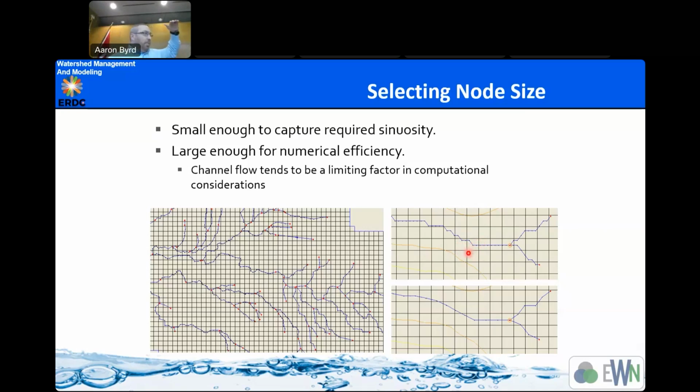Now, if on the DEM the flow direction was diagonal, you have √2 times your DEM size, 1.41. So all of a sudden you have varying sizes of your stream node cell lengths. That make sense?